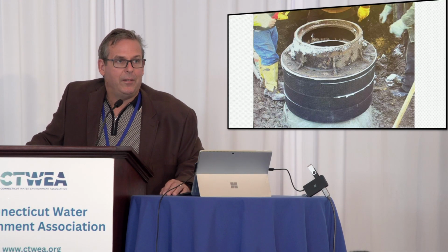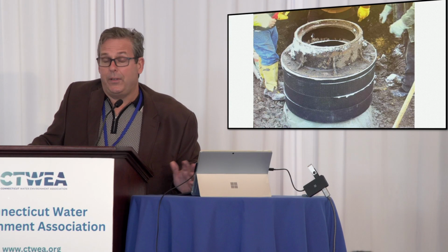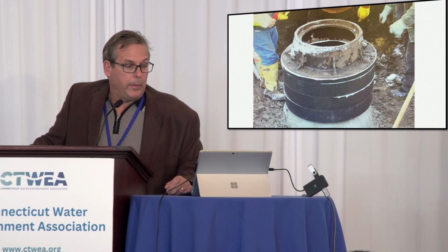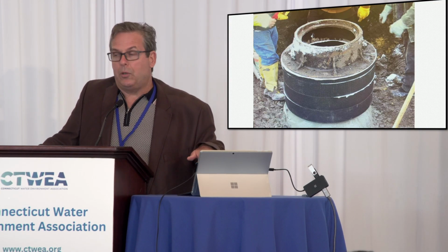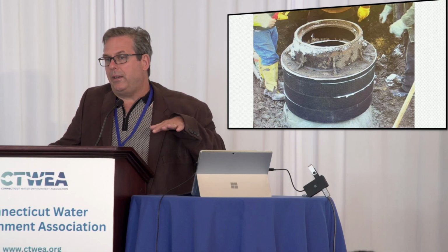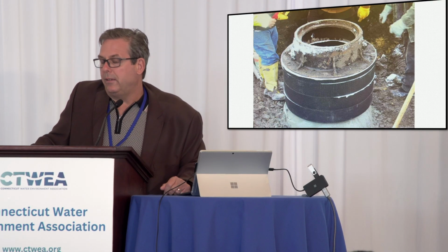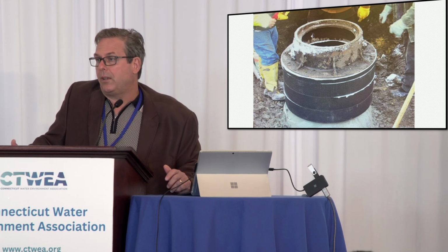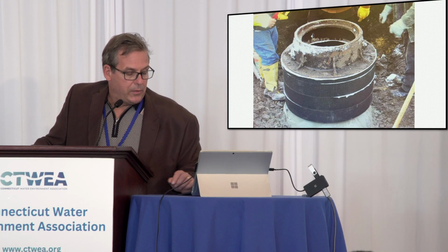On high water years, they've inundated these manholes and they've flooded over. So what we had to do was use the pro rings. We've raised the manholes 3 feet from grade and then put the watertight manhole frame and cover on it, and we've seen a significant positive result from that.